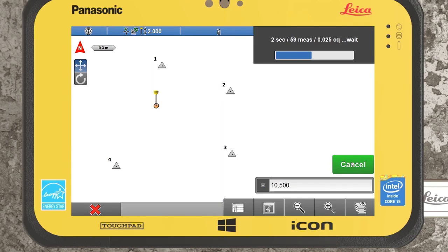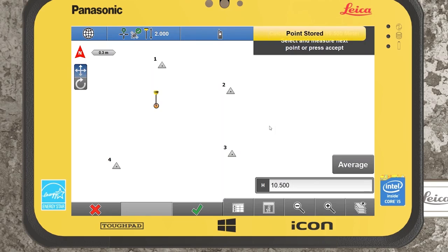If I select average, we can see it's going to record average measure point. So if we're using the standard GPS, we'll hold it straight. However, if we're using the tilt, it doesn't really make a difference. If you have a bipod, that again would be more advantageous. Once we're happy, you can see there can be no residuals assigned if we're just recording a height transfer because there's nothing to compare it against. There's no known point. We're just defining what it is.